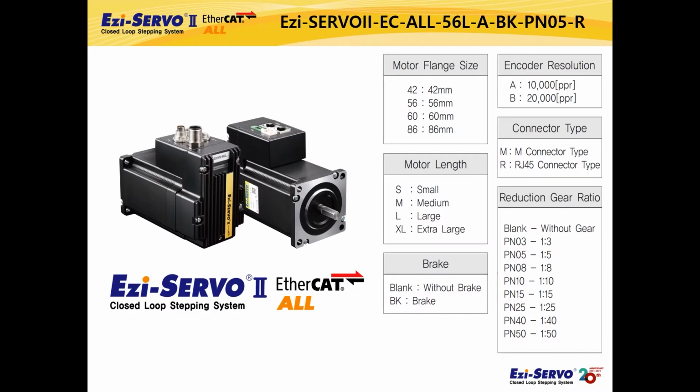First of all, I will explain the combination model name of the Ezi-SERVO II EtherCAT ALL product. In the example model name, EC means the product using the EtherCAT network, and ALL means an all-in-one product that combines a motor, a high-resolution encoder, a drive and EtherCAT network. 56 means 56 mm motor flange size, and L means motor length. A means a product with 10,000 ppr encoder applied.